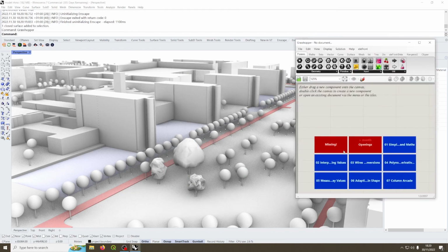And we'll do something very similar to what we did for our abstract trees with a few modifications. One thing that's important is that you have to have the Elephant plugin installed in your Grasshopper. And you can just find that by Googling Food4Rhino and Elephant and then download the plugin. Let's start by referencing the trees from Enscape in our Grasshopper document.